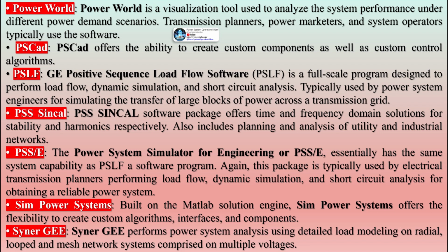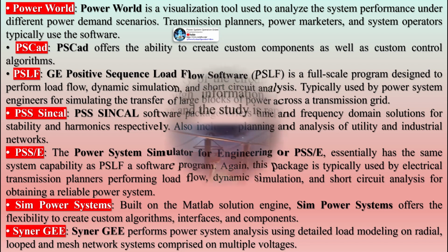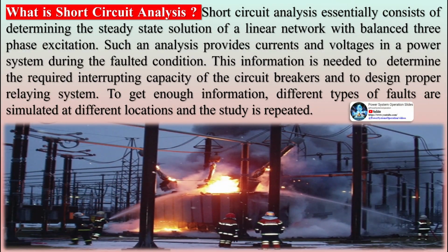Short-circuit analysis service: support of IEC 60909, IEEE 141, ANSI C37, VDE 0102 and 0103, G74, and IEC 61363 norms and methods, calculation of short-circuit currents in DC grids according to IEC 61660 and ANSI/IEEE 946, superposition method, including dynamic voltage support of generators connected via power electronics, multiple fault analysis of any kind of fault including single-phase interruption, inter-circuit faults, fault sweep along lines, etc.